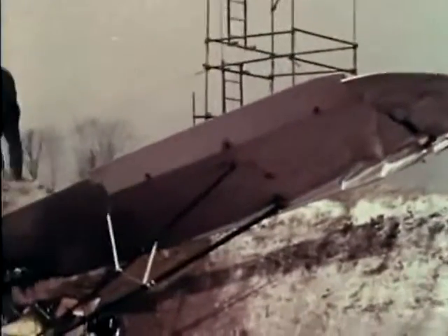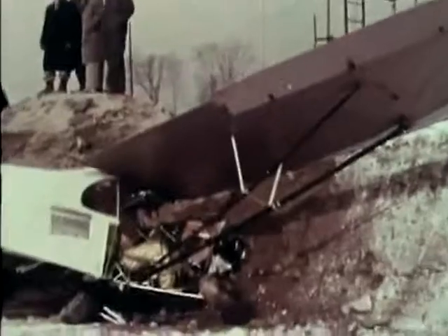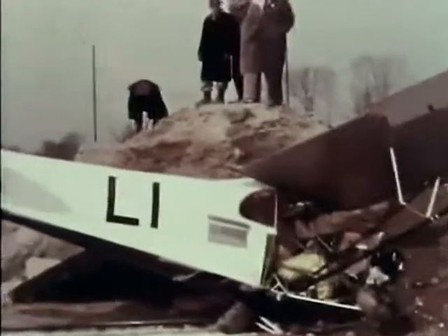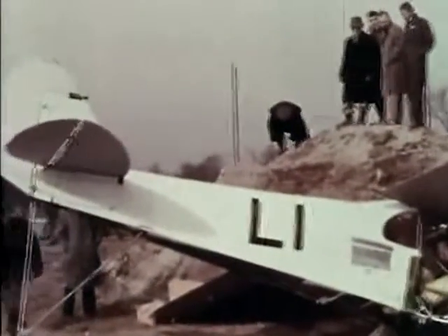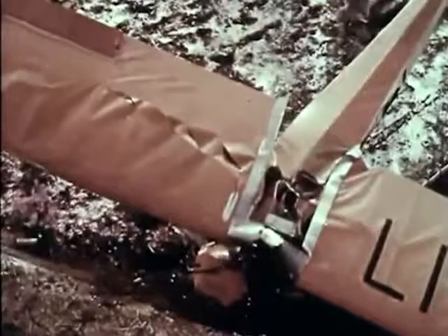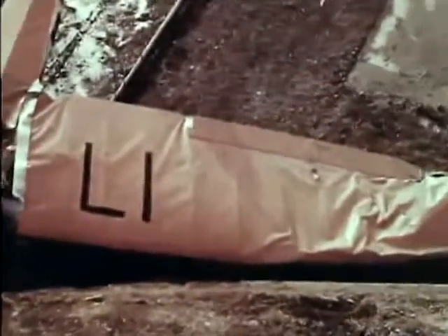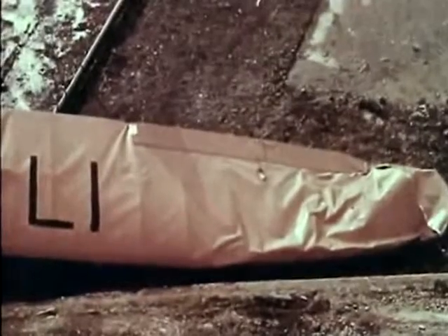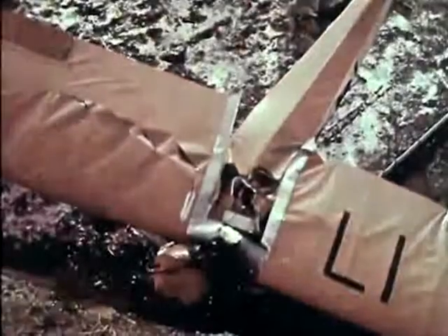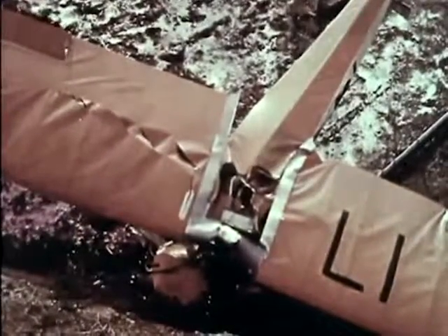The extent to which the crumpling of the fuselage force structure reduces the deceleration applied to the cockpit floor can be seen by comparing the deceleration of the engine with that of the fuselage floor in the 60-mile-per-hour crash. Notice in the next motion picture sequence that the engine deceleration rises immediately upon impact, whereas the floor deceleration rises gradually until extensive crumpling of the fuselage force structure has taken place.